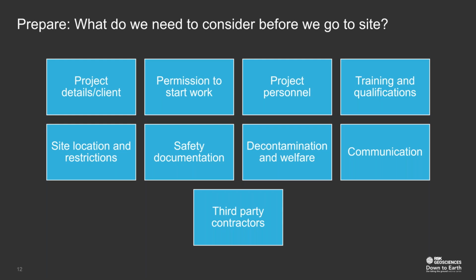That was a lot of acronyms there. So CDM stands for the Construction Design and Management Regulations 2015. I'm not going to be able to cover the ins and outs of this talk, but it was first introduced in 1994, revised in 2007, and recently updated in 2015. Virtually everyone in a construction project will have legal duties under CDM. There's more details on the health and safety website, and there is a very handy AGS guide for CDM in the geotechnical industry. This is just a 2-page document and really worth reading.